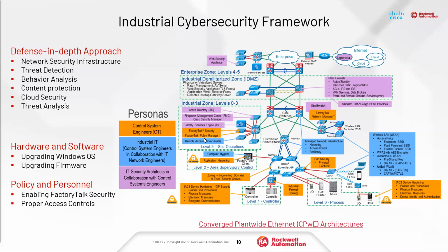As part of PlantPAx, we provide virtual templates that have the software pre-installed, and it also comes standard with a specific version of Windows. In most cases, right now, the templates that we have are Windows Server 2016. If you have a Microsoft Windows license, in most cases, they allow you to upgrade to the latest versions. So if I talk to a customer that has Windows XP, they're still supporting Windows 7.